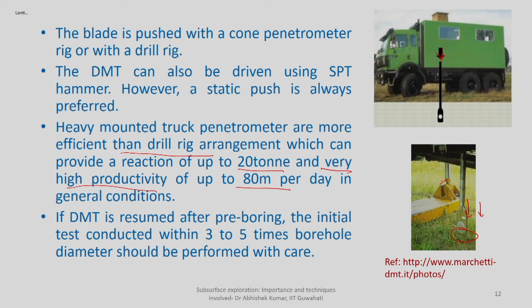Again, you can see here, in order to avoid any lateral movement, once the reaction frame reaches the desired location, you provide a more stable platform. This avoids any lateral movement of the truck assembly during the test. If the DMT is resumed after pre-boring, the initial test conducted within 3 to 5 times the borehole diameter should be performed with care.